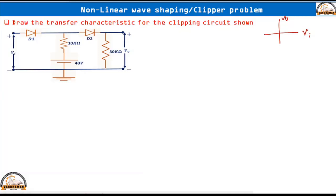Now if you observe, diode D2 N side is connected to ground through a 30 kilo ohm resistor, and diode D2 P side is connected to the 40 volts DC battery through a 10 kilo ohm resistor. For example, you did not apply any voltage, that means Vi is equal to 0. Diode D1 N side is connected to 40 volts again through 10K, but if you make the P side voltage of diode D1 0, that means Vi is equal to 0, what will happen? We will see once again.